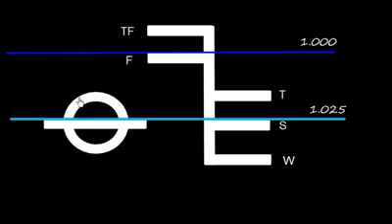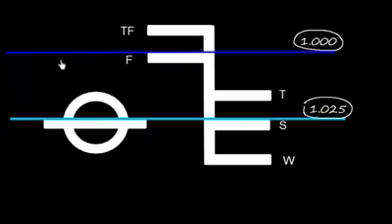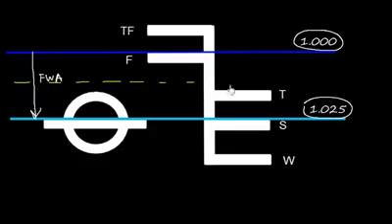Now let us revise this concept once again. The vessel is in salt water here, and here the density is fresh water. If the vessel was in fresh water like this and comes to salt water, this distance is freshwater allowance. As the dock water density is between 1 and 1.025, let me mark here the dock water density.